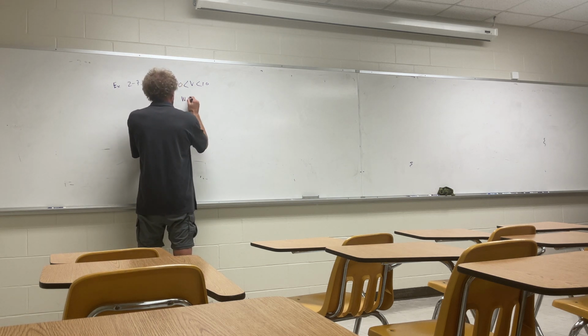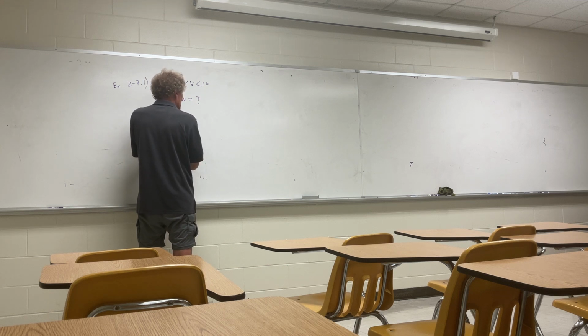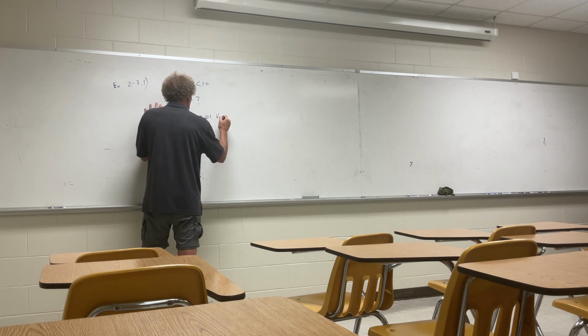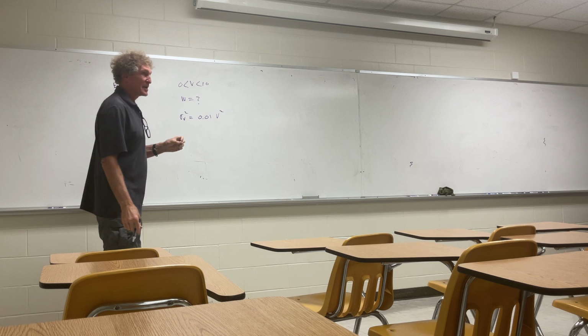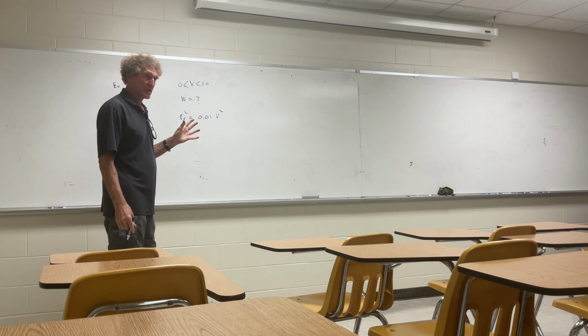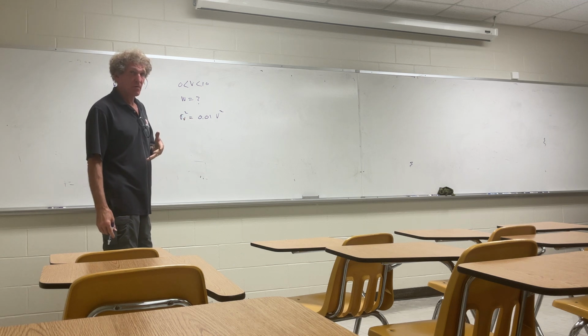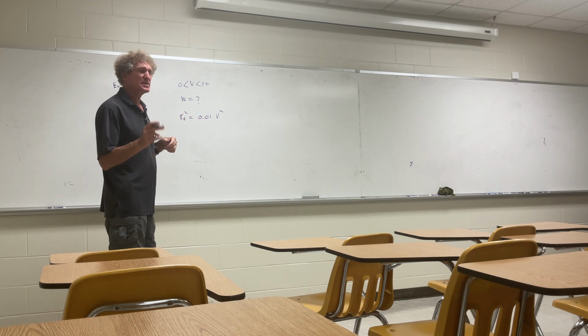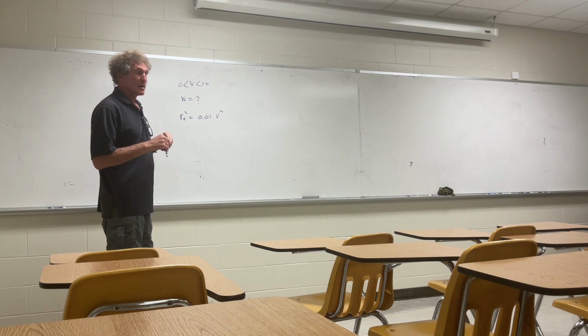We don't know. Okay. And what does he want? How many discrete levels are required for the mean square value of the quantizing error to be 0.01 volts squared? All right, now, you see the mean squared and the variance are the same, because the mean is 0. Y'all follow me on this, class? Does he say mean squared? Yes.